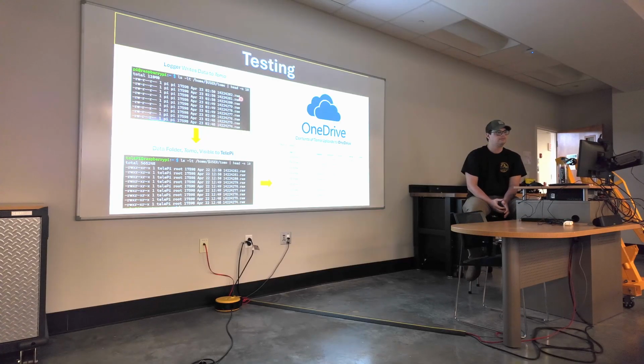More questions from you? You mentioned that the LoRa uses the ISM band. Do you know what band the Wi-Fi and the Bluetooth are using? No, it's off the top of my head. Same band. It is? Okay. So there could potentially be interference as well. Mm-hmm. Yeah, everything you don't pay for is ISM. Really? Pretty much. That's kind of what distinguishes it. Those are the free bands, the ISM bands. Gotcha. Everything else, cellular, you pay for, because they use bands they actually have to pay for. Right.